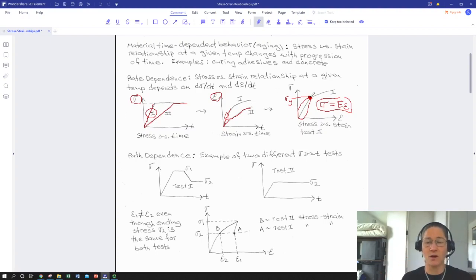It is permanently deformed. That permanent deformation is what is known as plasticity, and it's how we're able to form things. So it's a good thing if we're in manufacturing and we're trying to form something and turn it into a new shape. If we are designing a structure to be used in service, typically we don't want that to happen. So as engineers, almost all of our design is going to go on in this realm, in the elastic regime, because we don't like things yielding and permanently changing their shape and surface. That can lead to bad things happening. Ultimately, it can be the prelude to failure.